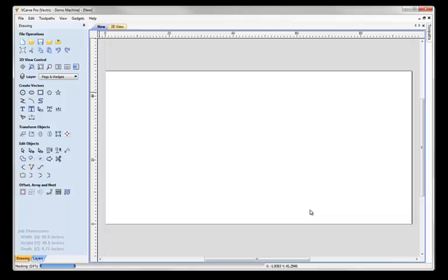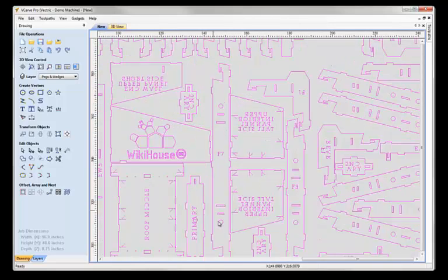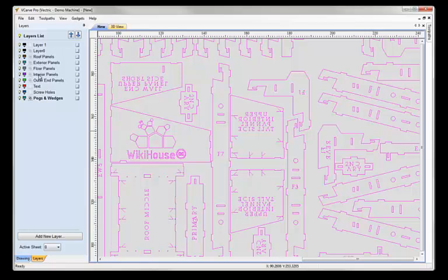So this again is importing the SketchUp model, laying all those components flat, but only subdividing them down to the level where they start with those double underscores in the component name. If we look up here, this component, F7, is one of the main beams on the model. And this part up here, the S-joint so-called, was a component. Each one of these little tabs was a separate component, and what we've done on this import is weld those all together to get a single boundary. We've also respected all the layers of all these parts as they came in. And again, that's very important, as we'll show, for automated machining of these parts.